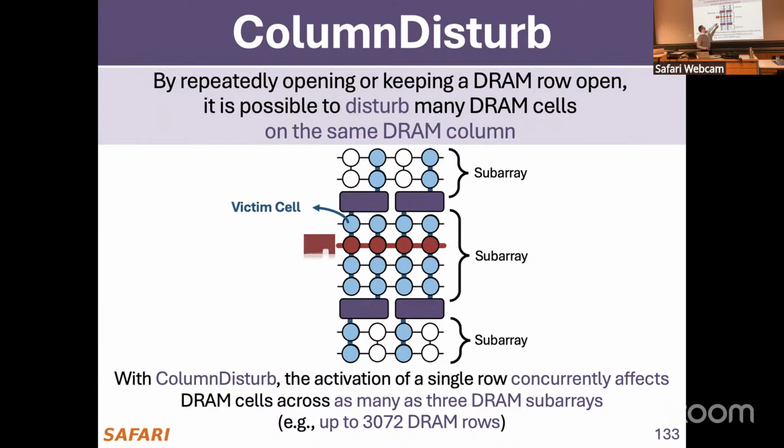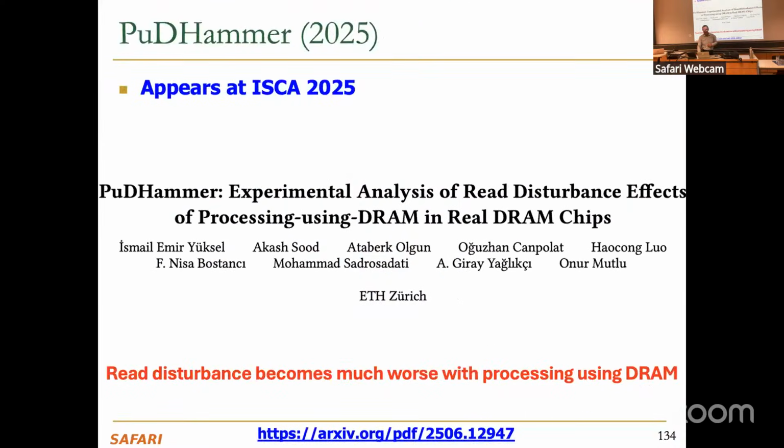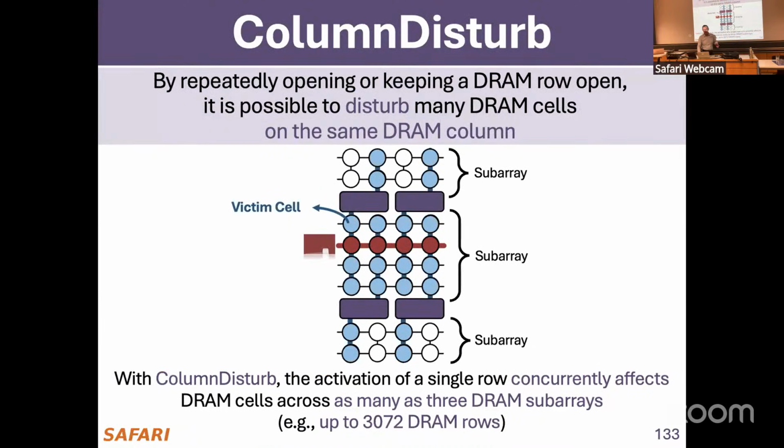Basically, it refreshes a few physically adjacent rows, right? It doesn't refresh, it doesn't think about even the other subarrays, right? RowHammer doesn't extend beyond subarrays. So the question becomes, how do you actually solve this problem? So this is actually interesting.